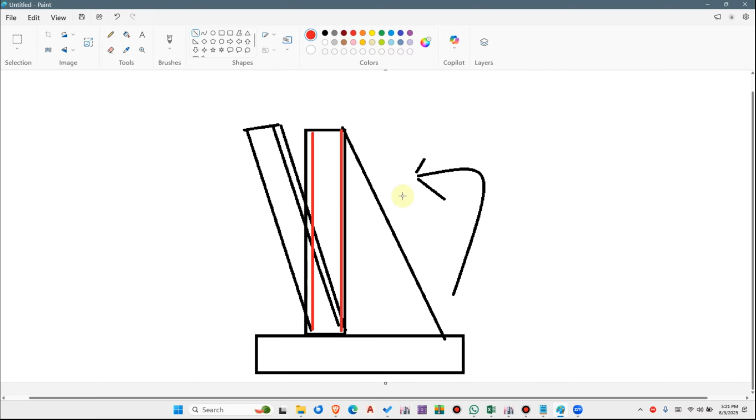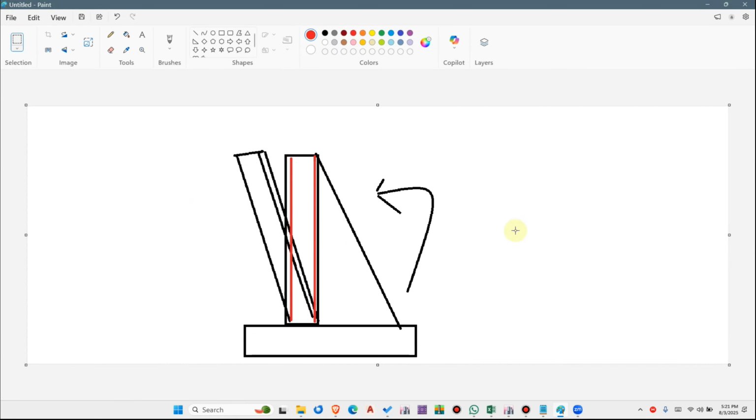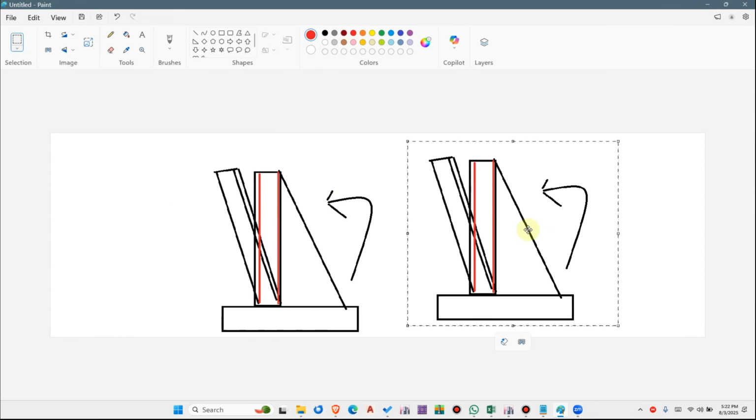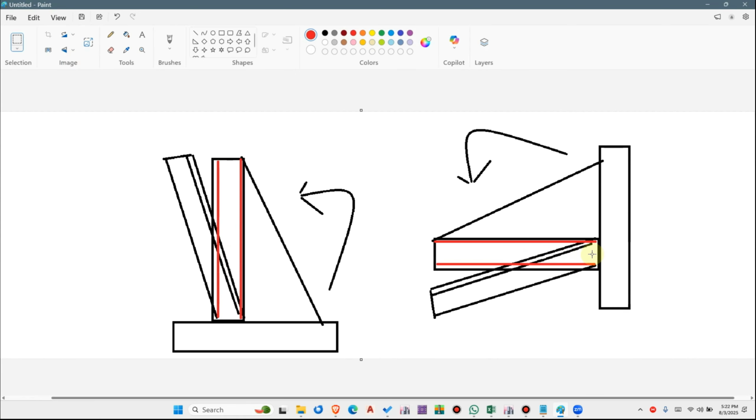Okay. So basically, if we reverse this, this is the bending moment you can see, and this is the maximum bending moment. It is 830 kip-ft or 829 kip-ft for the D wall to load combination. Now, if we rotate it, then it will be a beam, right? Rather than a wall, we can analyze it as a beam. There is a cantilever beam.